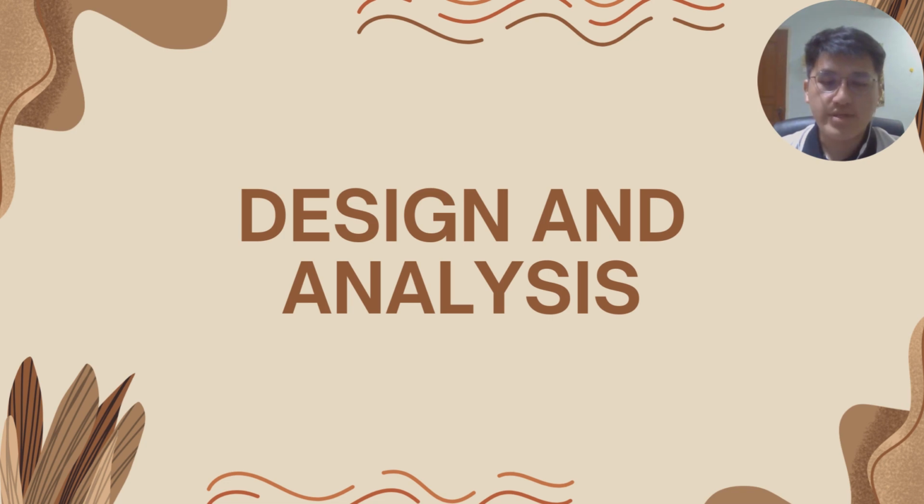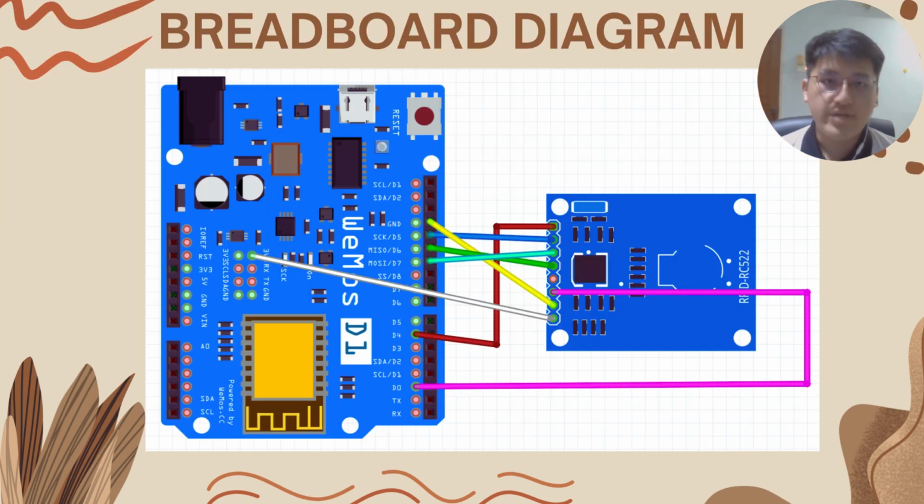My name is Che Jin, and I will be presenting about the design and analysis of the smart shopping cart system. So this is a breadboard diagram for the connection between the Wemos D1R1 board and the RC522 RFID reader. We will start off with the D7 pin. The D7 pin on the Wemos D1R1 is connected to the MOSI pin on the RC522. This will enable the data transmission from the microcontroller to the sensor.